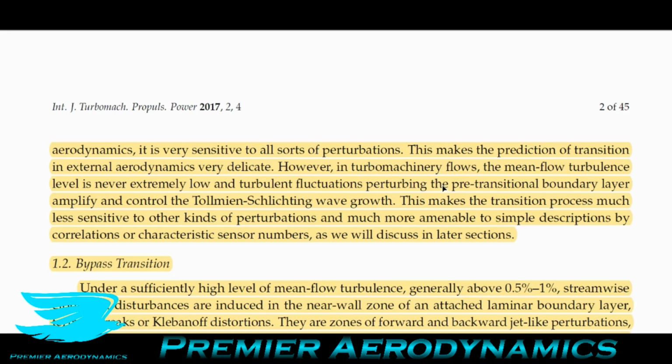RANS and URANS, some of these models, generally speaking, are not capable of just modeling everything. If you have a certain situation, you need to use a certain turbulence model. As I've mentioned in other podcasts, my favorite is K-Omega, because that is the most robust I've come across. That's the one that you can really just set and forget. It does a pretty good job with everything. Even then, it does fall short sometimes, but that's usually due to mesh grid resolution. Still, you should always pay attention to what you're using.